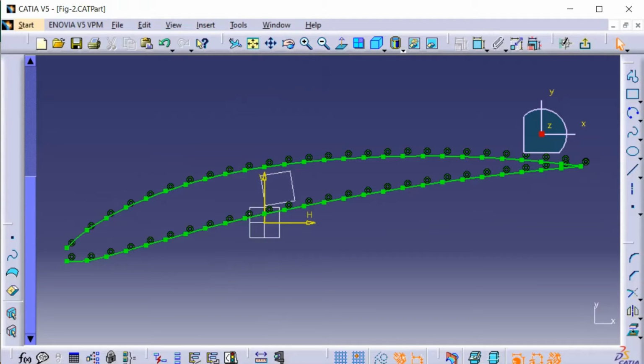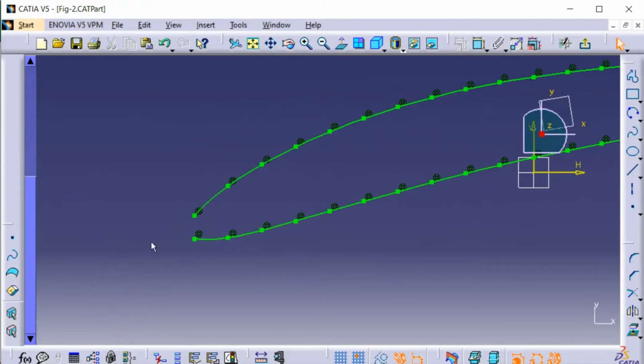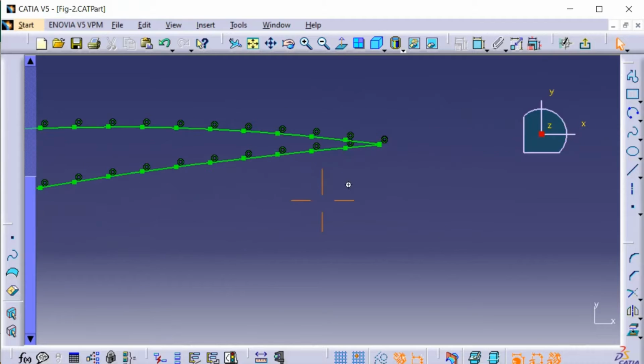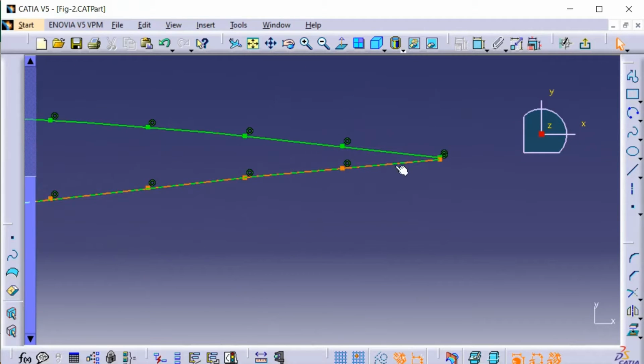The case 2 is for longer profile data. Here the coordinates may be overflowing and pass the leading and trailing circles. If you see here, you cannot identify it, but if you see the trailing side, you can see how sharp this is. So if you form an arc, it will form somewhere here. So this data is actually the overflowing data. In this case, we will not get a perfect arc if we connect the endpoints of the leading or the trailing endpoints of concave and convex side.